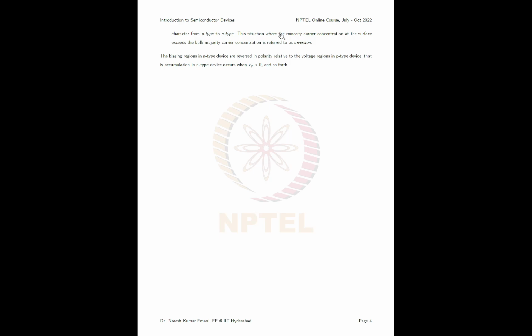This situation, where the minority carrier concentration at the surface exceeds the bulk majority carrier concentration, is referred to as inversion. And if you change your substrate from P-type to N-type, your gate biasing will also get reversed accordingly.